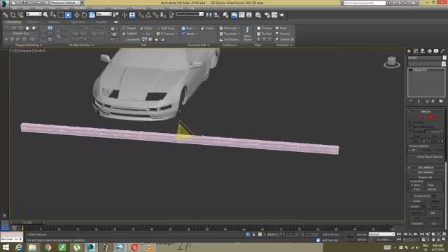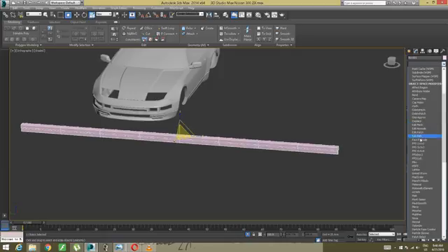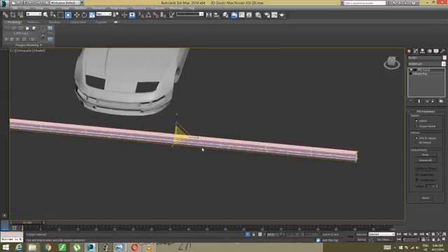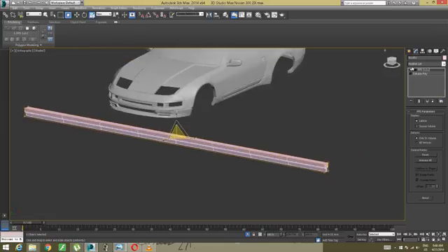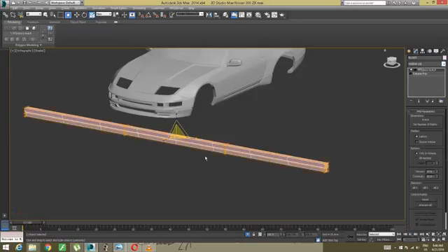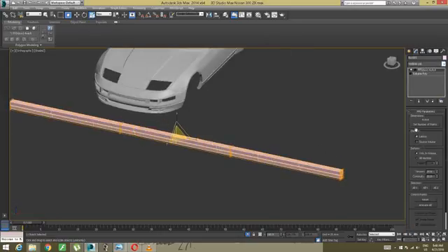I'm going to go into one of the modifiers and go into this right here. And now I just want to go into here, lattice, control points. So I'm just going to get rid of this right here. But I'm going to go into the FFD modifier right here, FFD box, and I'm going to try to set numbers right here, approximately to be